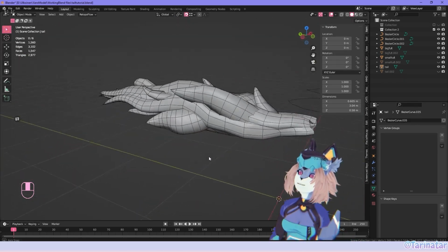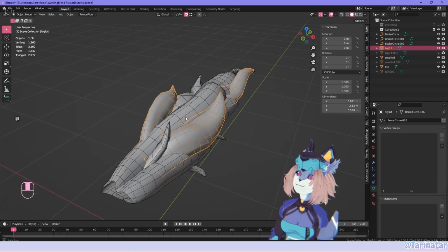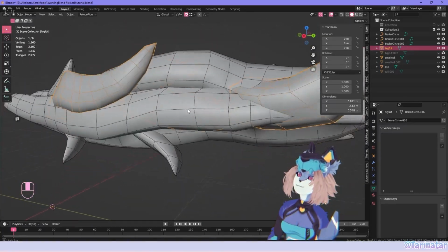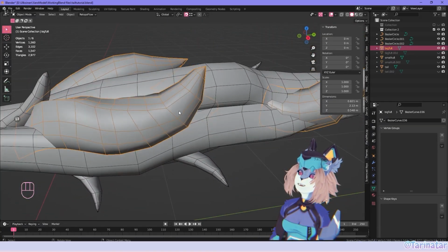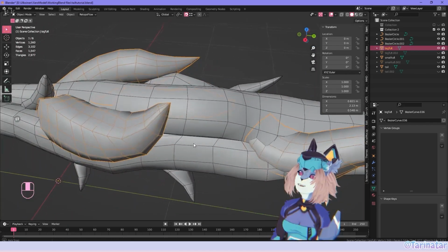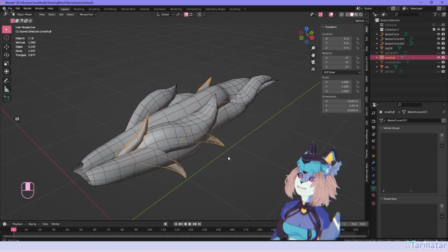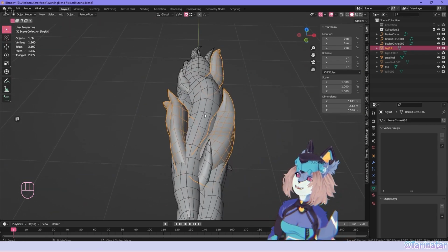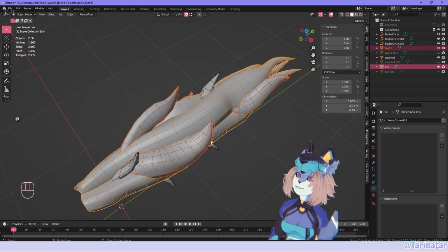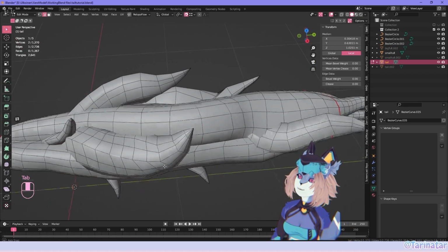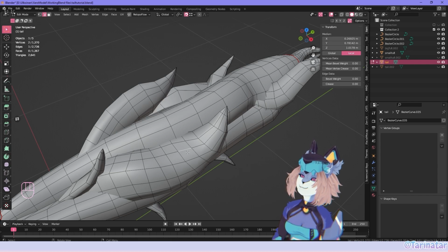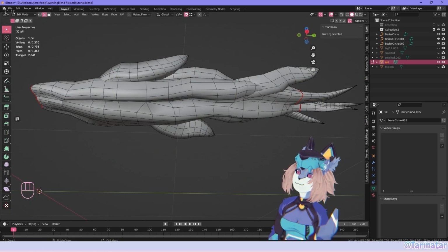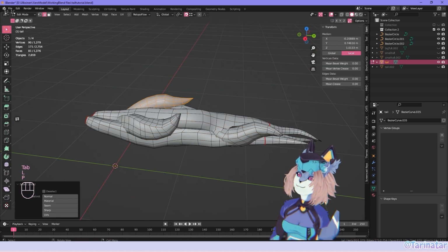I think I would go and merge these bigger ones to the geometry, simply because they add quite a bit of redundancy, meaning there are parts inside that don't need to be inside. So I will be doing that, but the small parts we can keep as separate. I'll repeat the same parts as before, but I will first merge it with this object. Okay, and when you join objects like that together, you can still link select these as separate because they don't share vertices with the main shape. Have them attached one by one.